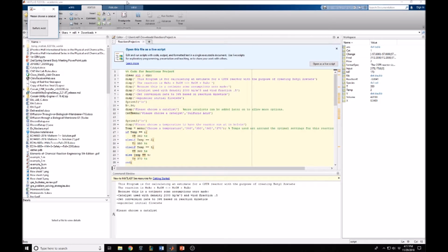Phosphoric acids are sometimes employed, but it leads to rather slow reactions. Soluble or supported metal salts minimize side reactions but usually require higher temperatures than strong acids. With sulfuric acid, the reaction reaches equilibrium faster and is used in more continuous reactions, for butanol included. Other catalysts that have been found so far would be Amberlyst 15. So, let's pick our catalyst.